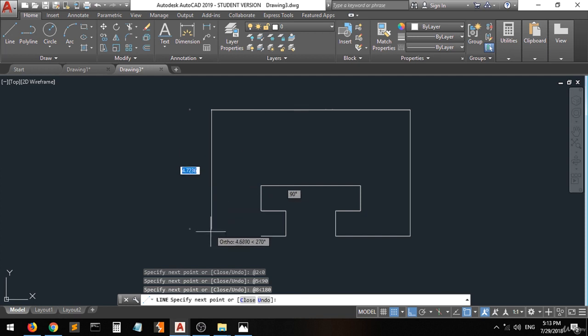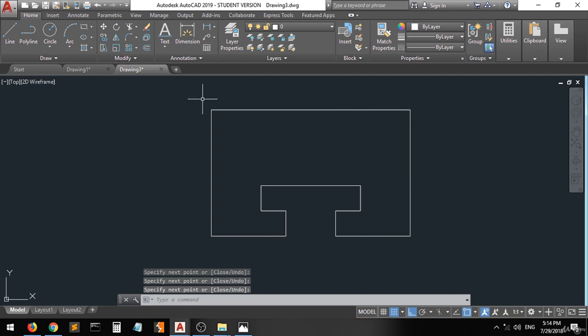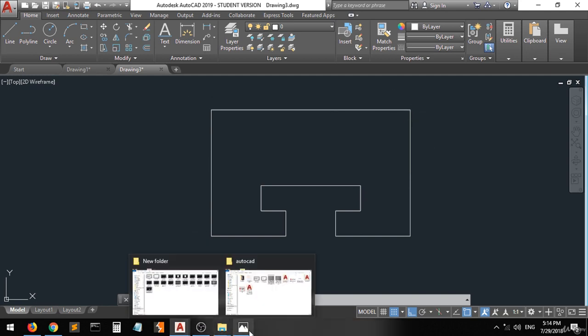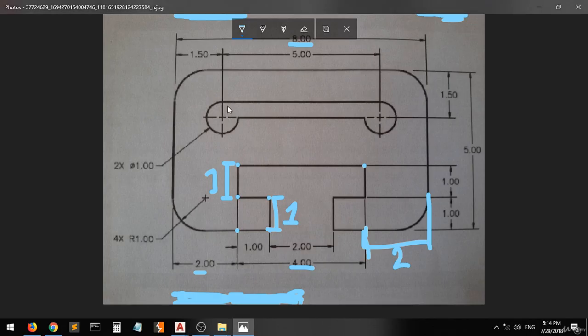Excellent. And then we'll move here and use snapping mode to here and click enter to end. Now we'll do the fillet thing, and then we'll go back to create these small details in here, okay?